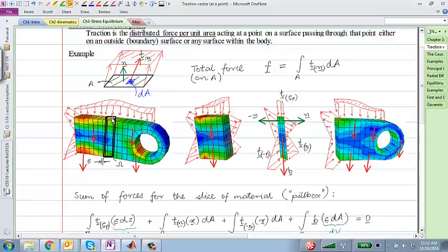Similarly, on the top surface of this slice, the normal is pointing in the upward, or outward, direction on that edge. So T sub epsilon gamma is the traction coming from the distributed external force up here. There is T minus n. So let's say this face has a normal towards the right of n, and therefore to the left it would be minus n. And traction on the face with a normal minus n is given by this distributed traction. Similarly, traction on the face with plus n is this. We have some body force, and those are all the forces acting on this slice.